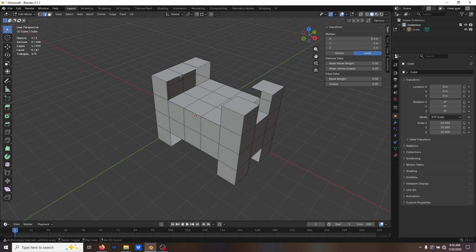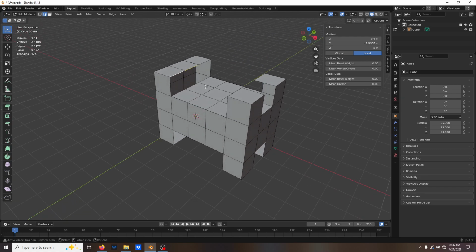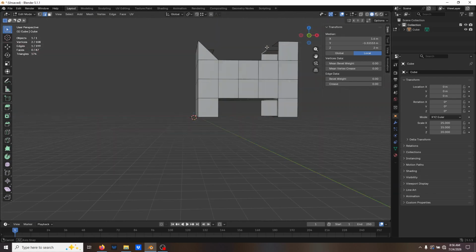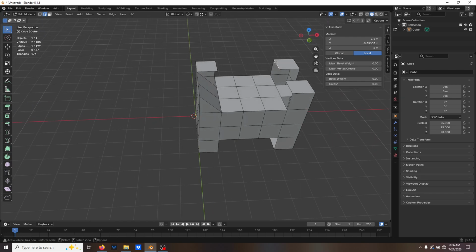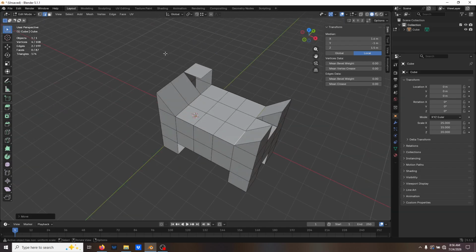And you can rip vertices too. Yeah, you can rip faces. It's just remember that whenever you select a vertice, edge, or face, it's really just a combination of vertices for that. So I'll grab these and bring them right there. There we go. And then I can grab these. And actually, this would be nice if I had left auto merge on. So we can do that, and then we can finish that.